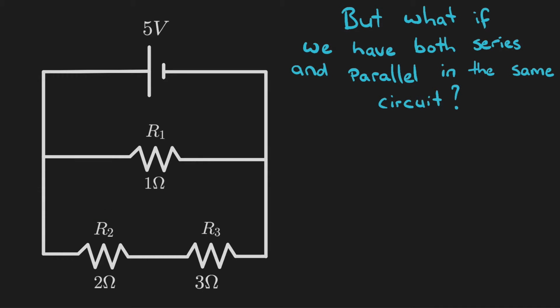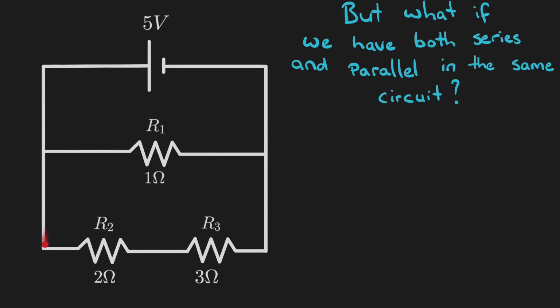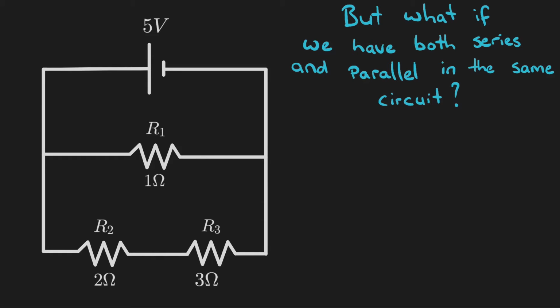Individual branches, the equivalent resistance in individual branches, rather than just the equivalent resistance overall, straight off. So I like to tackle it by working out the series resistance, the equivalent resistance in the series circuit, and then we'll have one resistance in this branch, and then we'll have a parallel circuit, so then we can find the equivalent resistance in both.